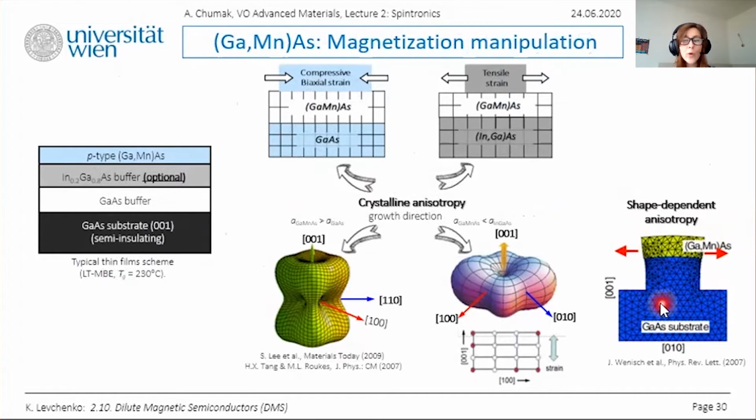It's usually done in the case of the in-plane magnetization or compressively strained case. So we are creating a pattern-induced magnetic anisotropy caused by the misfit relaxation, which takes place perpendicular to the lithography-patterned nanowires. And in this way, the spins of the magnetic ions are aligned along the wires, pointing this way. Hence, introducing an additional degree of freedom that can be used in some spintronic operational devices.